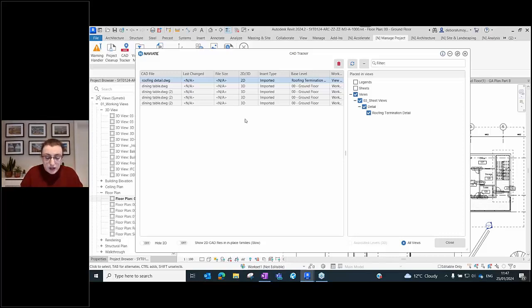I've often come across situations where a CAD has been imported into a Revit model and it's been hidden in the view. Somebody's brought it in to trace over it and they've hidden it then and forgotten about it, and the view gets duplicated, and so the import gets duplicated, and that spirals through the model, and your models can get bloated over time if you have too many imports in there. And once they're hidden, then they're really difficult to trace back and basically find them all.